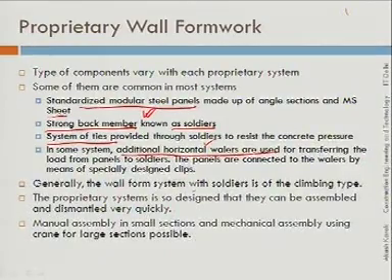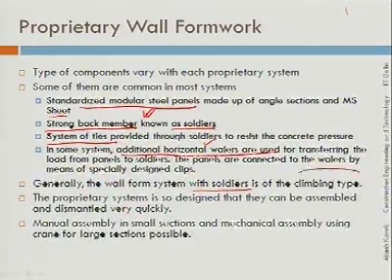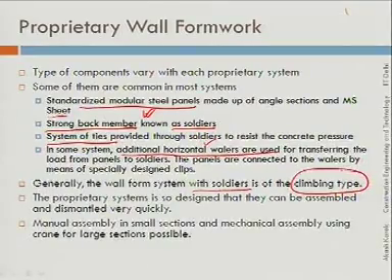Normally the soldiers are used in the case of climbing wall formwork. I will tell you what this climbing type formwork is in a few moments. Now, when you design these proprietary systems, they are designed in such a way that they can be assembled and dismantled very quickly.